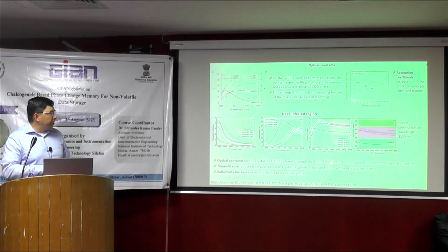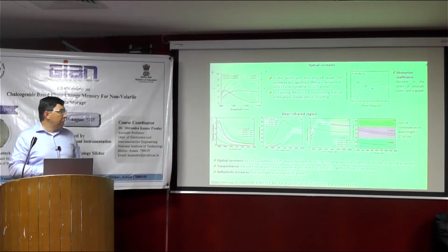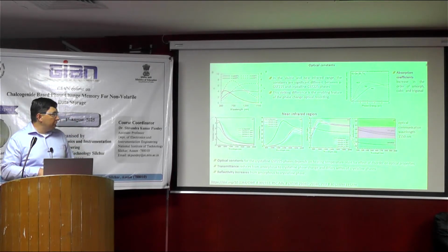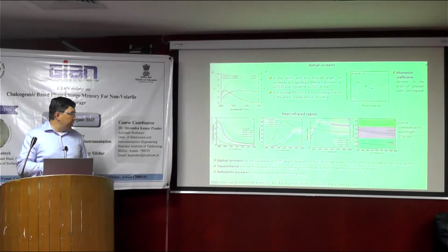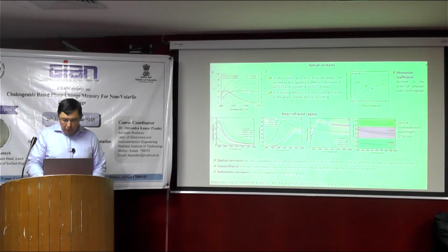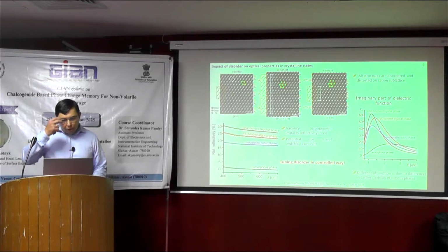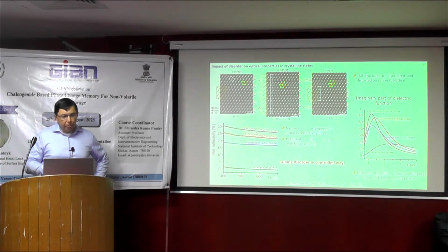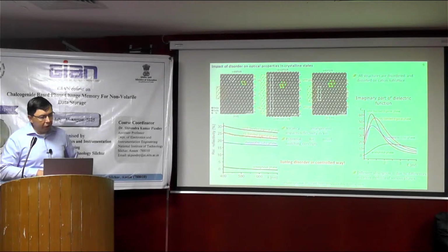Here it's written heating, but it depends on the structure, so on the defects or disorder, on optical properties. The transmittance is reduced from amorphous to crystalline phase change and differs between crystalline phases, and reflectivity increases from amorphous to crystalline phases. Here we can see more examples of these different properties of materials.